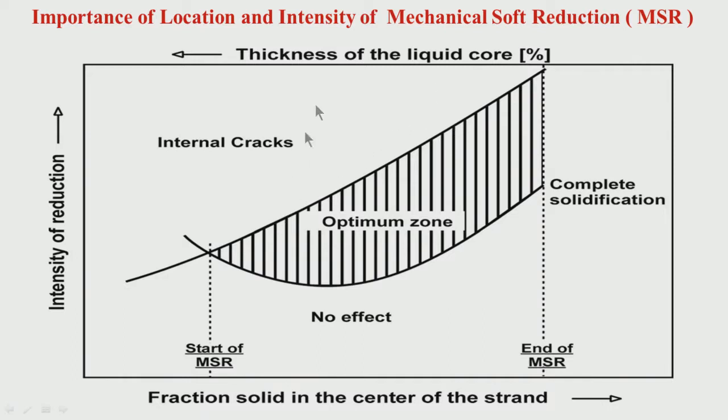Too much pressure will cause internal cracks. So you give pressure only to the extent which is optimum. You can find this out by trial and error. Initially use a small amount, then increase it, and see when the effect has started, and finally don't go beyond that. If you go beyond that, you may find additional crack generation in the shell.